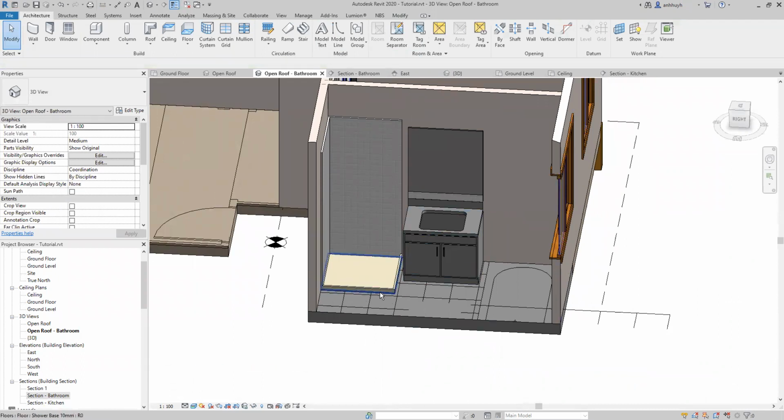So now we can see we need to add the glass panels, and we know that the height above the ground level is currently 10, which is the thickness of the shower base, plus 50, which is the height of this rim here. So a total of 60.